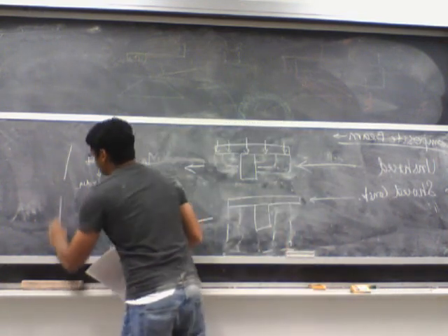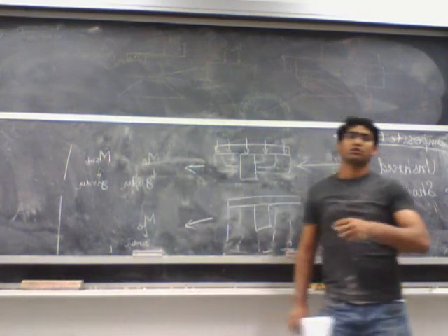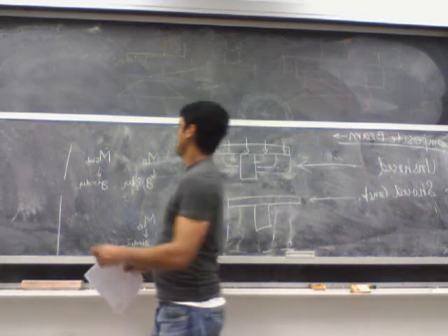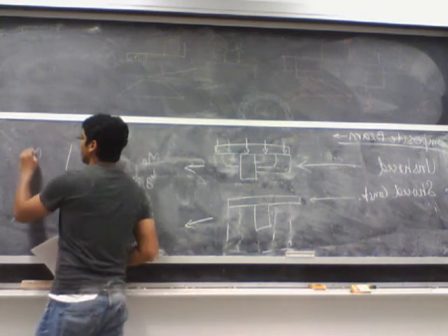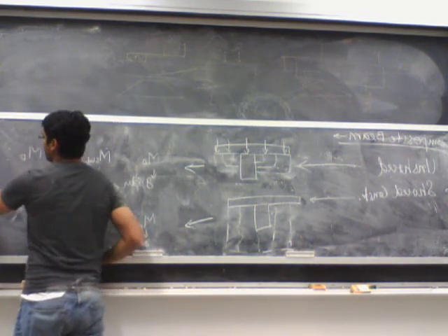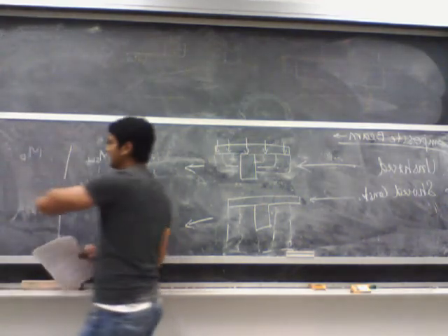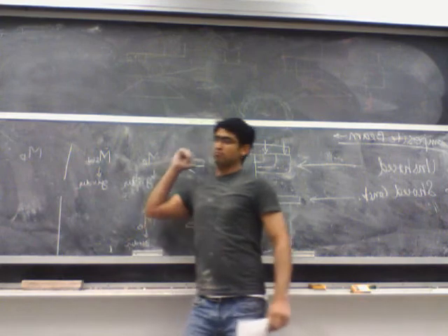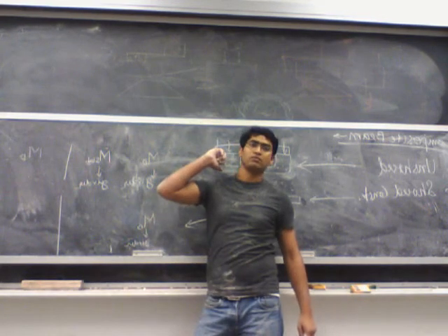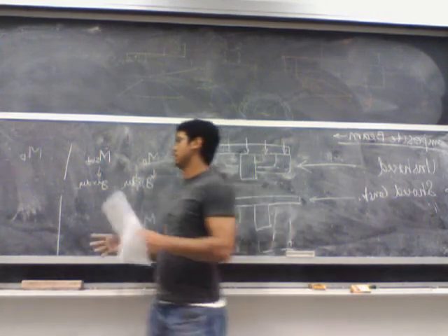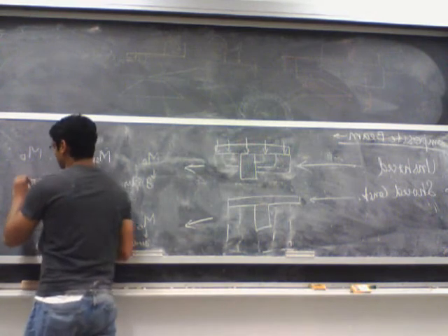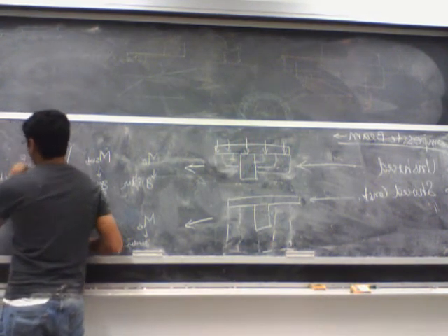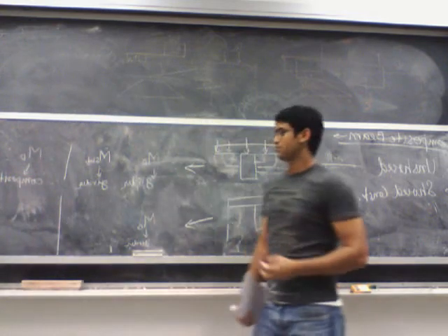Now, at service condition, you remove the shoring and apply your dead loads and live loads. So you have an additional dead load and an additional live load. What carries this load in unshored construction? It's carried by the composite action. The same for this case, right?